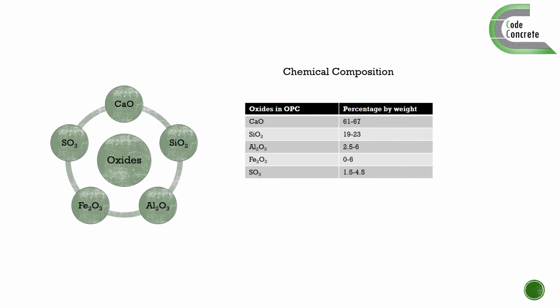Thereby, the chemical composition of clinker mainly sets the properties of the final cement product, which in turn determines the type of cement. Clinker is composed of 4 major compounds, produced from the chemical reactions between oxides during clinkering: dicalcium silicate C2S, tricalcium silicate C3S, tricalcium aluminate C3A, and tetracalcium aluminoferrite C4AF.